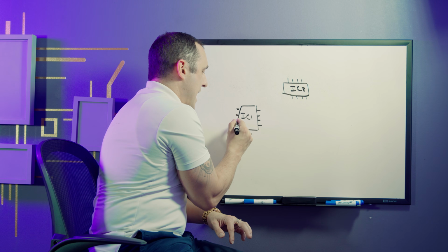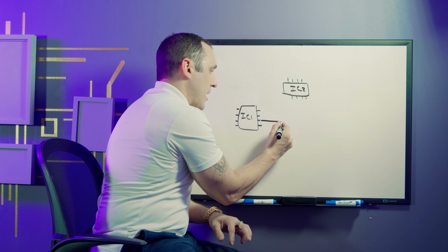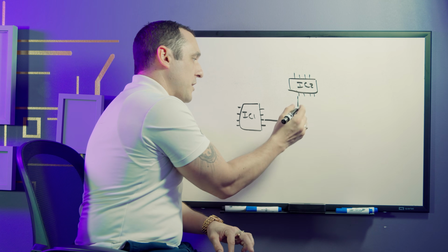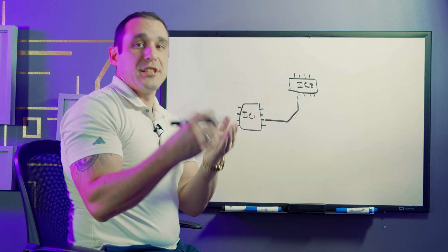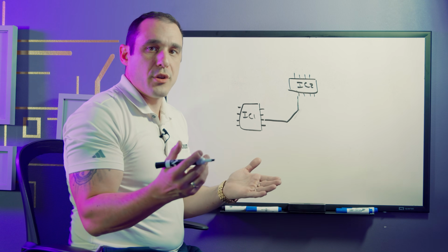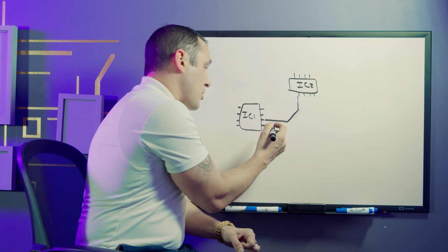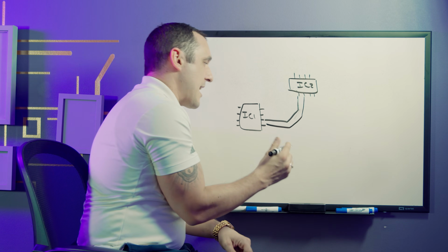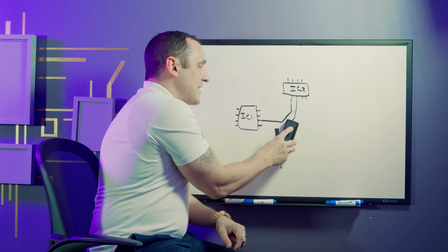Well, of course, your CAD tool will default to 45-degree traces, where you basically route a trace over this way, you route a trace this way, and then you finish the route going vertically here. So these 45-degree traces are, of course, very nice because they take up a little bit less space than a 90-degree trace. And I think that is one of the main reasons to appreciate 45-degree traces. I can then, of course, fit a lot of 45-degree traces here, just like this, between all of these pins on these ICs. But what about a 90-degree trace?